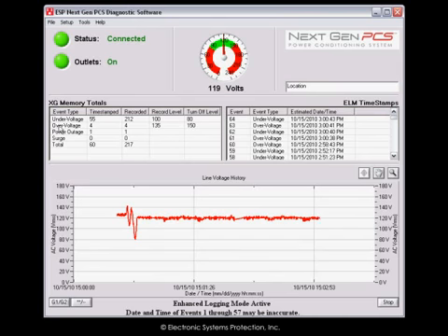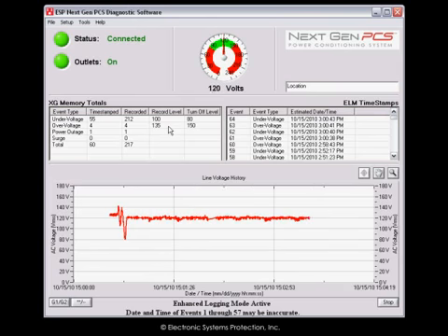The same thing applies to overvoltage. The record level is set at 135 in this case. The turn-off level, however, is not set until 150. So what this means is that the technician will see events recorded if they fall at 100 volts or lower, or from 135 volts up to 150 volts. So he can see recorded events in this range to see if there are some other anomalies that might be associated with this. And again, he may not necessarily want to turn equipment off at these levels.